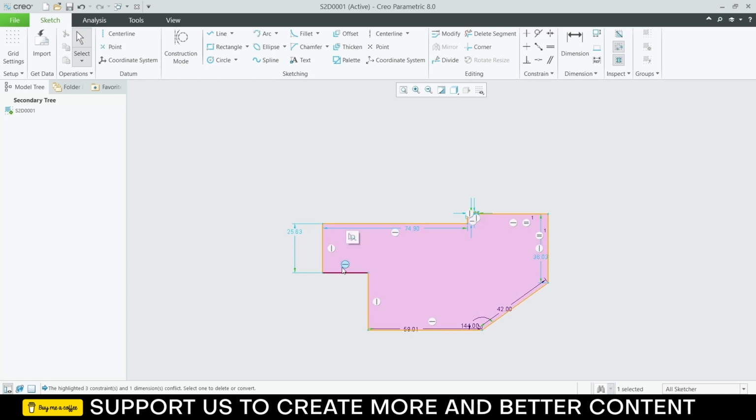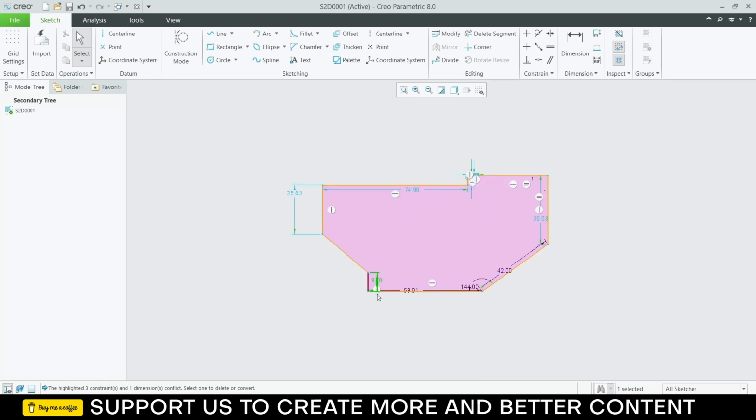Click on this vertical constraint because I need a slant height. Delete. Double click on it, type 9.78. This one will be 18.34. I'm not showing the drawing so that you can get better grasp what is going on, and it takes screen, and I don't have bigger screen. 46.